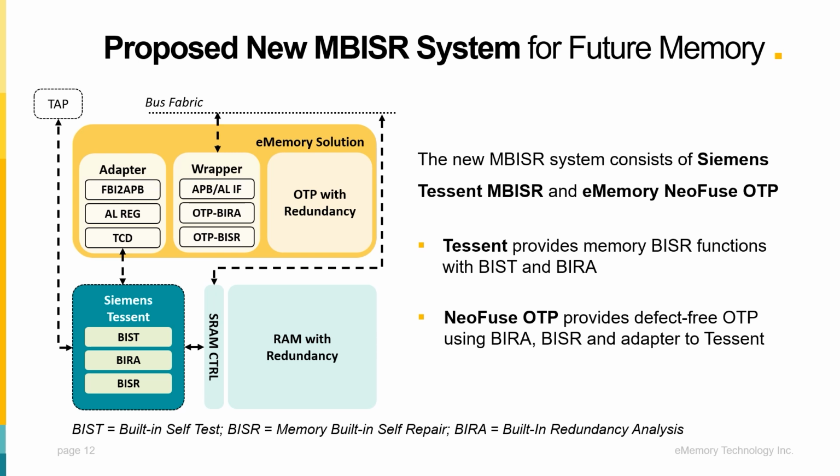Previously, the Tessent tool just used eFuse via a fuse bus interface. We have redesigned the connection interface by adding a synchronous interface for eMemory's OTP, and a universal interface to integrate with Tessent. This design enables the Tessent tool to use eMemory's OTP solution.